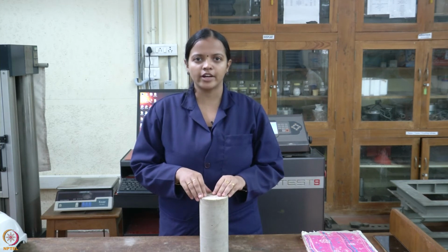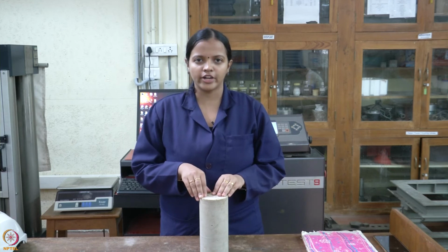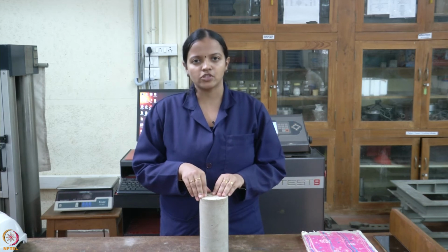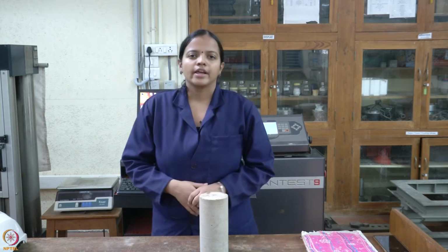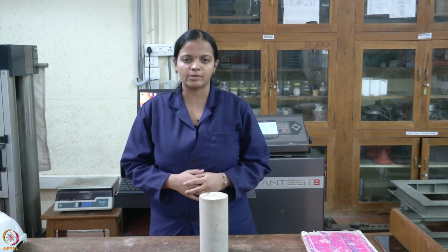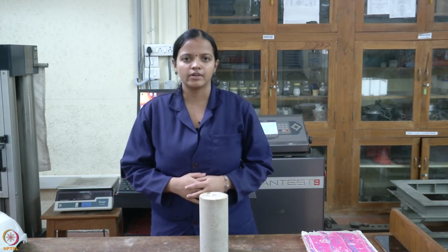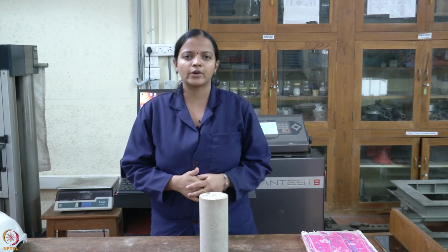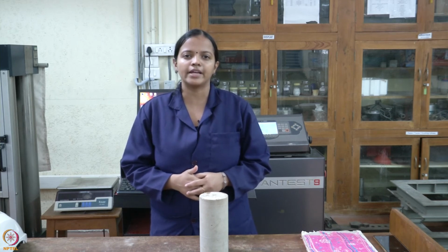From this test we can derive the Young's modulus of concrete. We can derive the Young's modulus of concrete from the linear region, and you can calculate the compressive strength of concrete. By using the axial and circumferential strain, you can calculate the Poisson's ratio, and you can also calculate the compressive toughness, which is the area under the complete stress strain curve. In conventional testing procedure, this type of result is not possible, where you can get the complete stress strain curve. By using closed loop testing, you can have a stable control and get the complete stress strain curve.